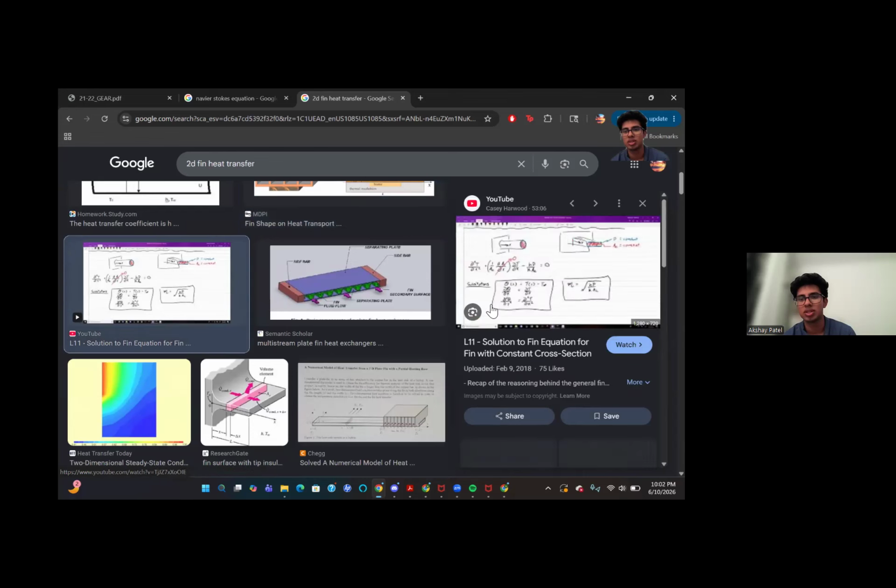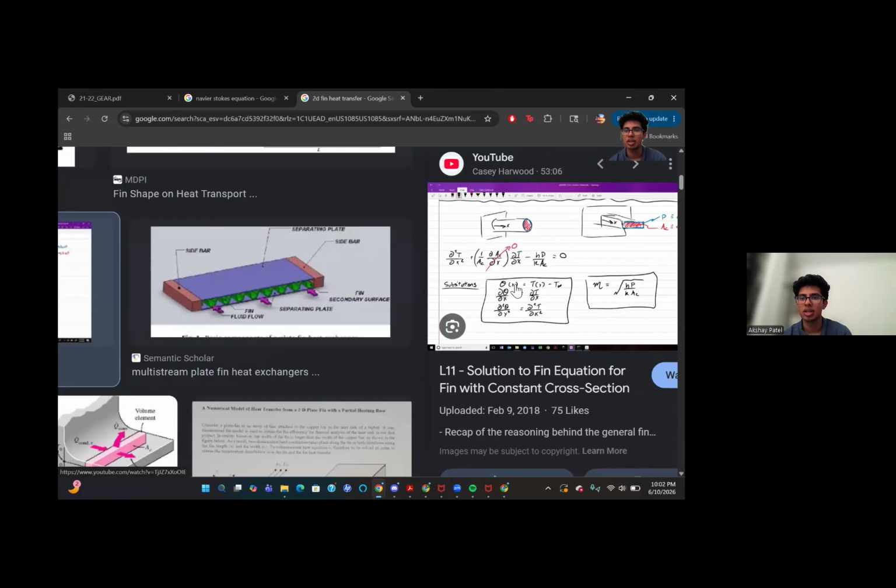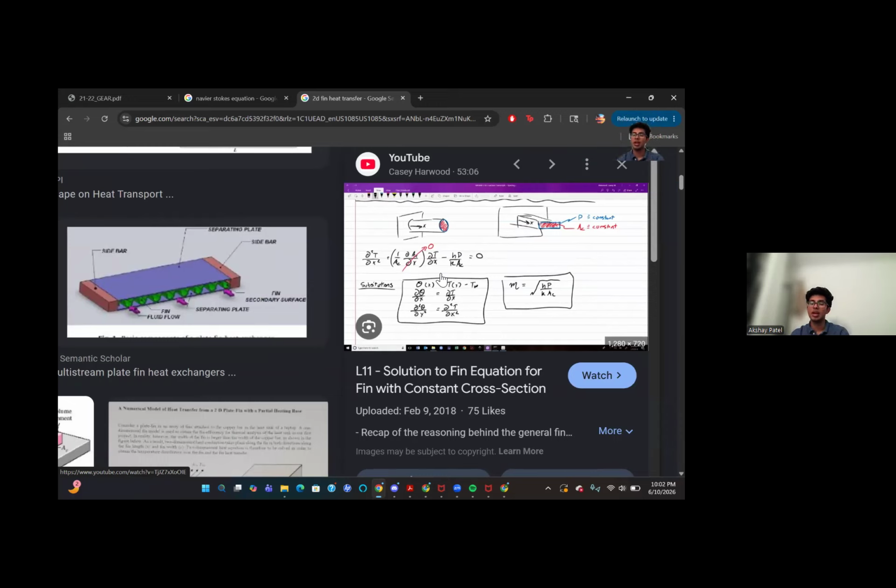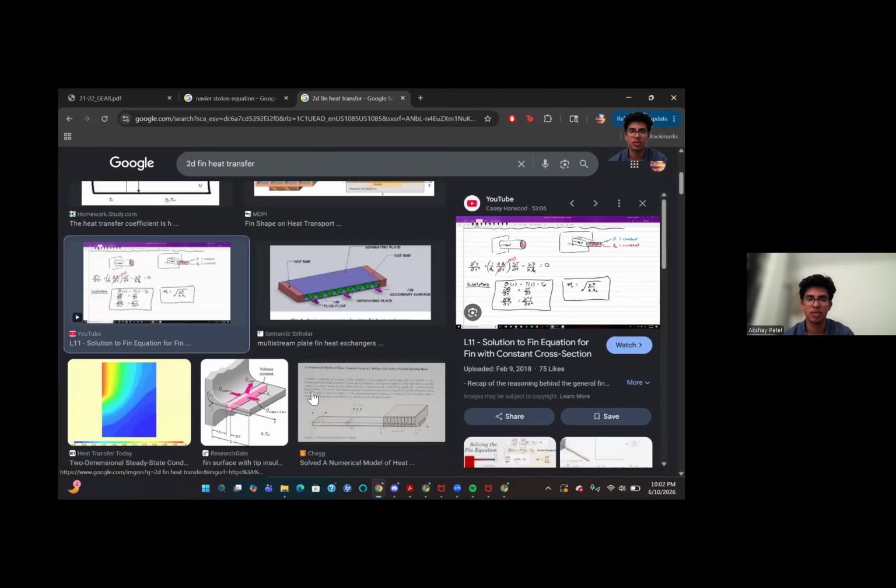So what are the equations then? It's similar to fluid flow, but there are analogous equations in heat transfer, and you make a bunch of assumptions and you solve these equations through. Again, you see these differential terms like temperature with respect to space. So at different parts of X, right? Your X is flowing outwards. Your temperature maybe drops down, so maybe your temperature is highest here and it drops down there. You basically want to know your temperature profile with X, so you know how long you need to make your rod and stuff like that. So you just use these equations and solve it through.